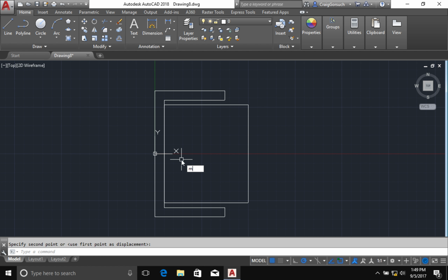And now I'm going to move that same rectangle one more time. Now remember, hold on, let me back that up, cancel out of this. AutoCAD remembers the last command that you used. The last command we used was the move command, so if I push return right now, it will start the move command again. AutoCAD also remembers the last objects you manipulated. So at this point, when it asks you to select the objects, you can type P and push return, and it will automatically remember that object. Really, it doesn't make a lot of sense when you're only selecting one object, but when you're selecting 400, it makes a big difference. So I'm done selecting my objects.